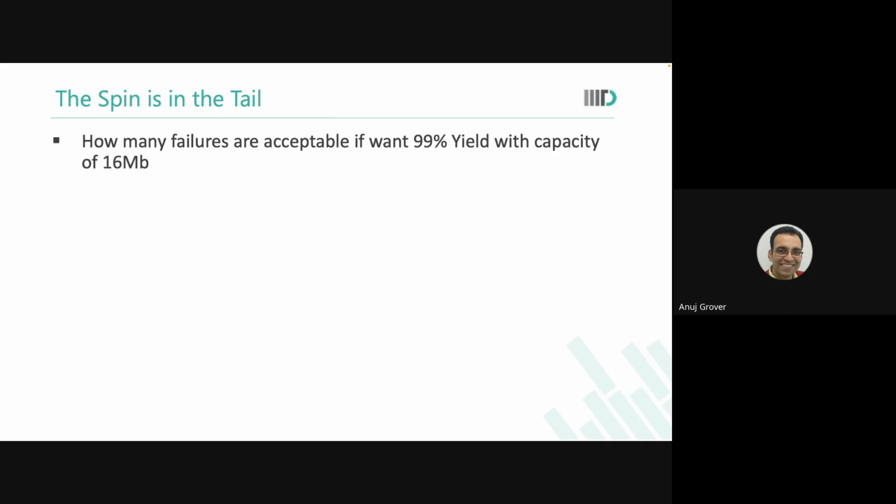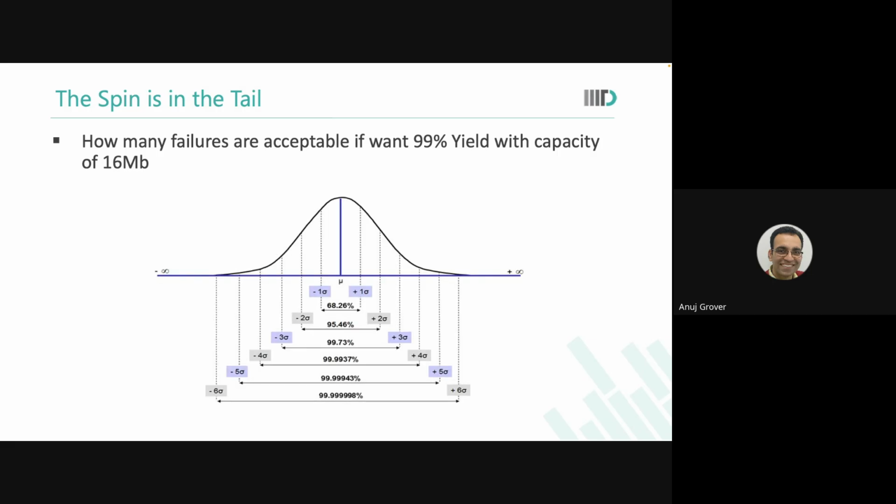So, yeah, if you have to have 6 megabit, then plus minus 6 sigma gives you 99.999999998 something fails. And so now, because Gaussian distribution is so well known, if you arrive at this conclusion that your SNM is Gaussian in nature or your right margin is Gaussian in nature, then all you need to find out now is a good estimate of mean and a good estimate of deviation.